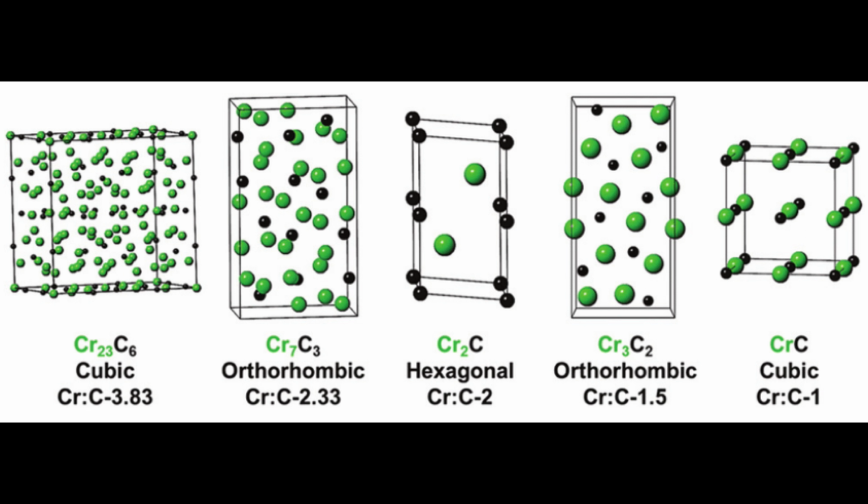That is to say, the spaces between the iron atoms are where the carbon resides, and now that carbon is trapped in there. And when the steel transforms, the crystalline structure transforms. It wants to go to body center cubic, but it can't because the carbon's stuck in the way, and so that's how you end up with hardened steel, is essentially by trapping carbon in the lattice or in the spaces between the iron atoms.